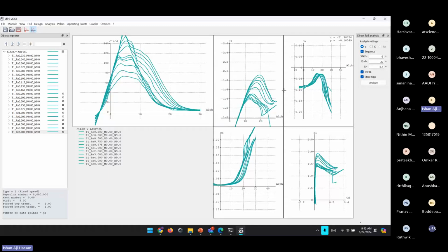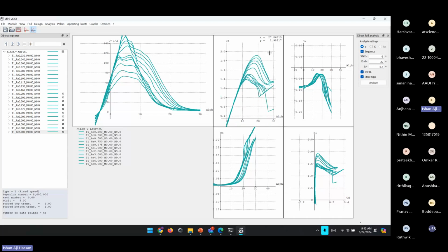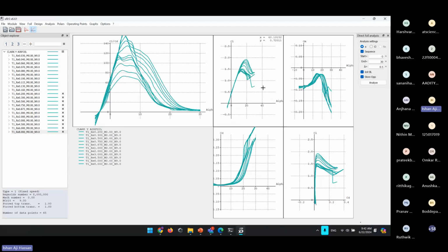Like I said, Reynolds number is pretty characteristic of airflow. It is kind of a measure of the viscosity of the air. So yeah, that is about the CL versus alpha graph. CM versus alpha you don't need to worry about right now because it's about the leading edge and not about the aerodynamic center for now. Still, we can see it's almost identical behavior with Reynolds number.